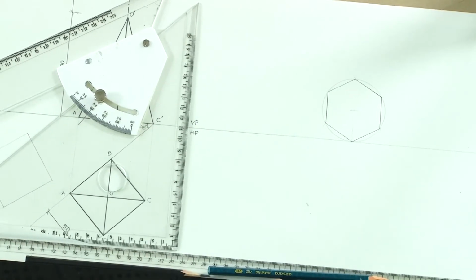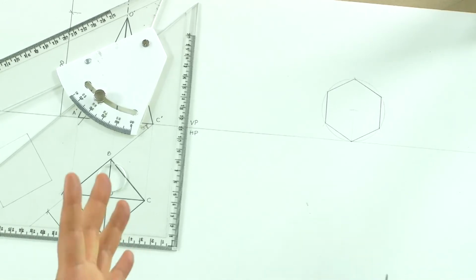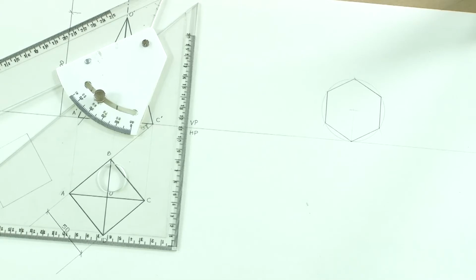So, this is the hexagonal shape based upon the condition that we have been given. This time we are not dealing with a pyramid, we are dealing with a prism, and this prism is perpendicular to VP. So, we know that the base of this prism is going to be seen in its true shape in VP, because the base becomes parallel to VP, which is what we have drawn. This prism is resting in HP on one of its edges, one of its sides. So, that is what we have seen.